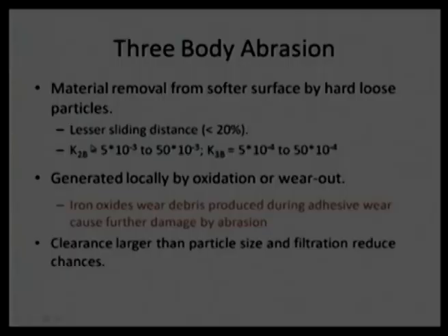That is why if I compare constant K for two body abrasion and three body abrasion, what are we gaining? This is wear rate, a non-dimensional number. Wear rate may be say 5 into 10 raised to minus 3. This is just an assumption. I am not saying that wear rate will be like this always; it depends on the material combination. But if the wear rate is something like 5 into 10 raised to minus 3 for one tribo pair, if I come to the three body abrasion, it will be reduced by 10 times. It will be 5 into 10 raised to minus 4.